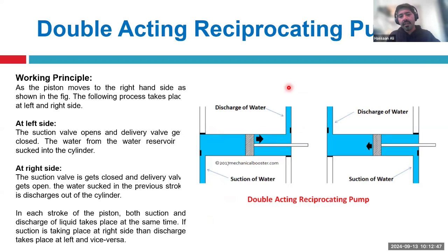And then similarly, in the second stroke, your plunger will move forward, towards the left hand side. The discharge port on the first chamber will open, essentially acting like a suction stroke on the second chamber. So you will discharge liquid into the second line and you will have the liquid enter into the second chamber.